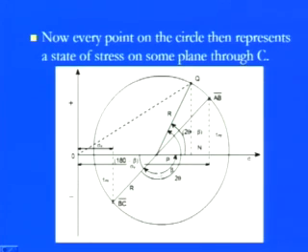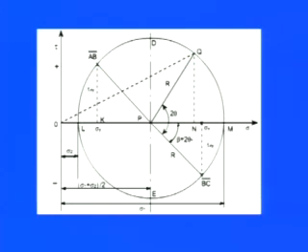Irrespective of whatever information you have, you can simply plot the Mohr circle. So now this is the well generated form of the Mohr circle. What we did here is simply convert the information we have: sigma x, sigma y and tau xy. Based on these three pieces of information, in the previous figure we showed how to plot the diameter and the Mohr circle. Now we converted that to where the minimum and maximum values of the normal stress component are, and those values are known as the principal stresses.